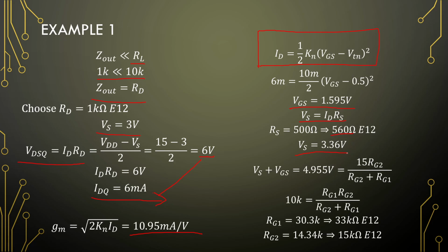Since there is a big difference between this big current and the voltage that it will actually deliver, it can negatively impact your amplifier if you're not careful. So I recalculated this value before finding our gate voltage.